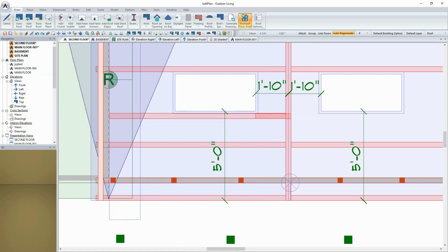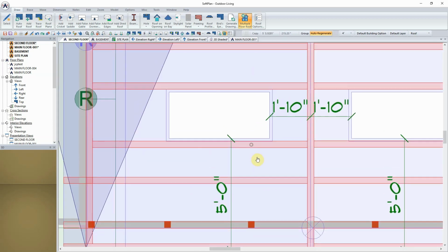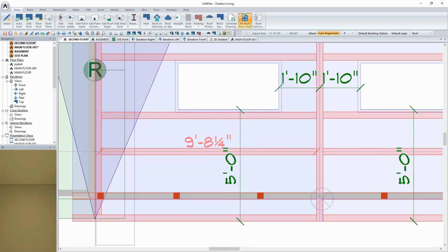Now at this stage right now, as I begin to put the framing into place, I can see that the roof as it stands right now, I'm just going to adjust a few of these rafters so that in essence they're running to the edge of the wall, as opposed to into the existing house that's there.